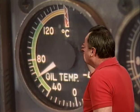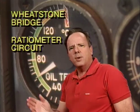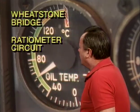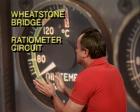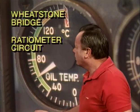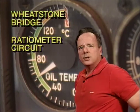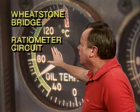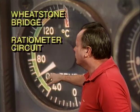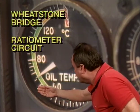Now, there are two methods to display the changing temperature, and one of those methods is what is known as a Wheatstone bridge. It takes that changing resistance, measures the change in current, and displays that. Another is a ratiometer circuit, which actually does the same thing. It takes changing resistance and sends the current in each direction. One direction gets more current, and an electromagnet moves the gauge over. So all you need to know for this is that a Wheatstone bridge and a ratiometer circuit are common ways of indicating oil temperature, and they do it by measuring changing resistance, and the result is the indication on the gauge.